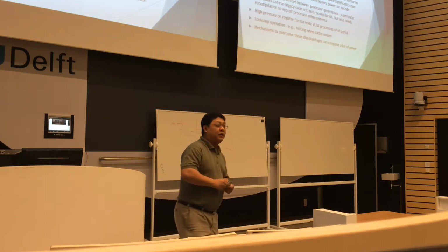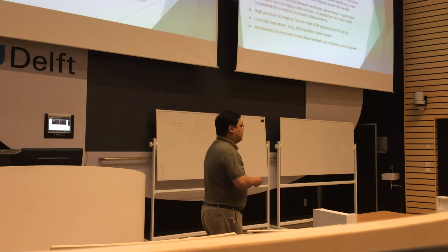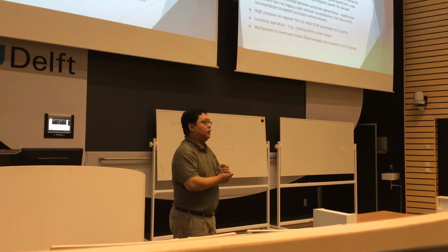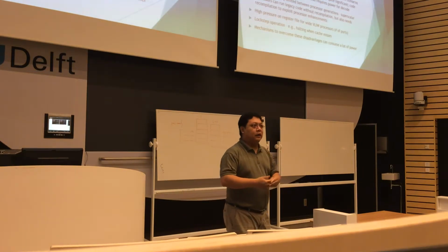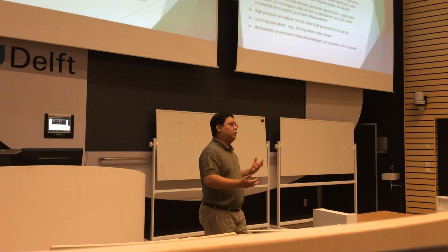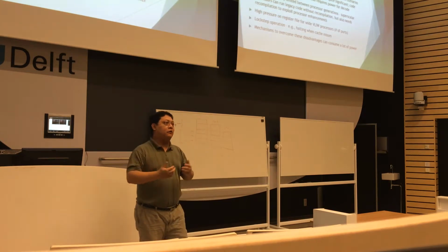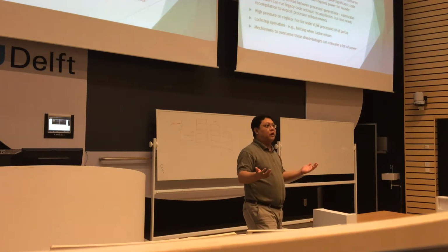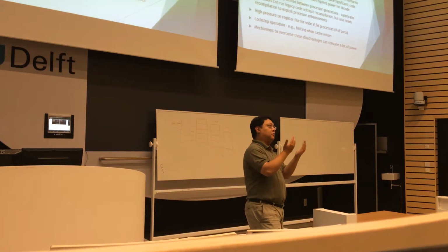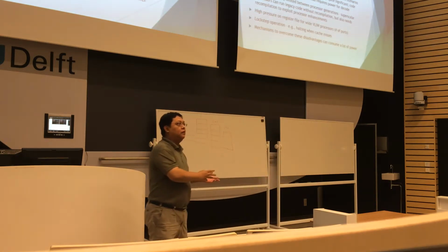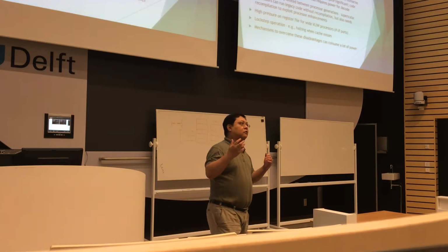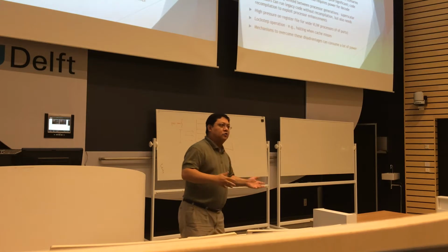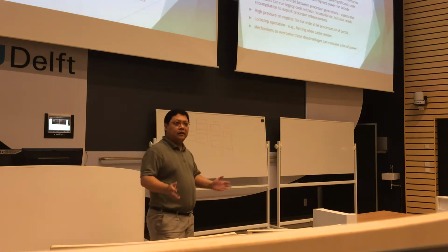Now let's go through a couple of disadvantages of VLIWs, the reason why they're not in general purpose, as we know. The thing with the VLIW is that you specify already beforehand what you want to execute. Usually in each data path you say this data path can do branches, this data path can do integers, this data path can do floating point. So the functionality of each data path is predefined, and what you do not want, of course, is to have each data path be able to do everything, because you will not use everything, and therefore a lot of power is wasted. So you would like to pre-specify what each data path can do, which is a limited set of the instruction set that you have. Now already this choice ensures that I cannot turn any program to fill all the slots all the time, in the same way that the superscalar processor also cannot fill all the slots all the time. It tries its best, but cannot.